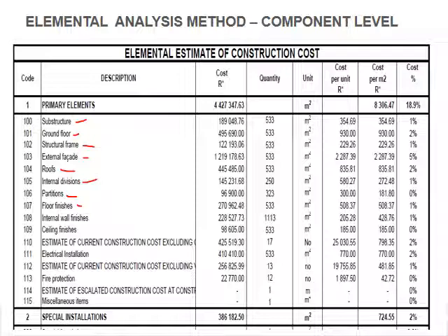This is usually how you build up your estimate. I didn't include the special installations and so forth, but your primary items are calculated here, and then you've got your quantities here, and you have your rate that you've calculated from your previous buildings, and you multiply that with your quantities to get your total estimate for the project.